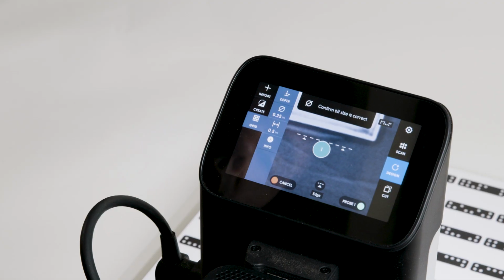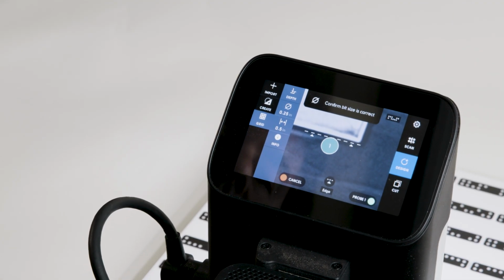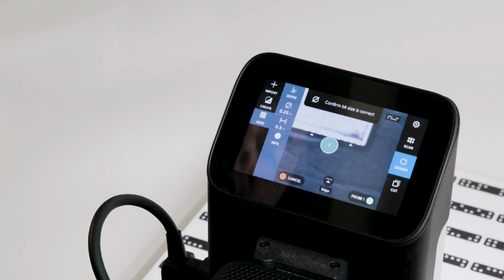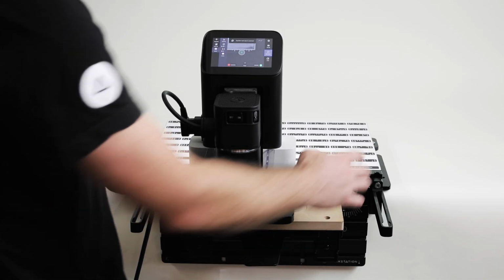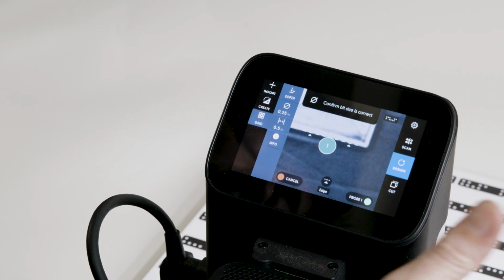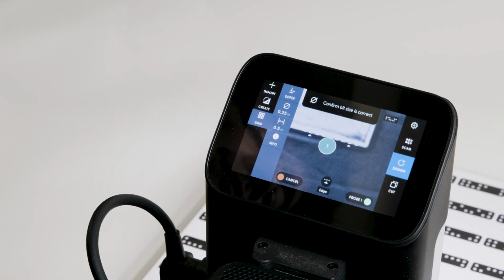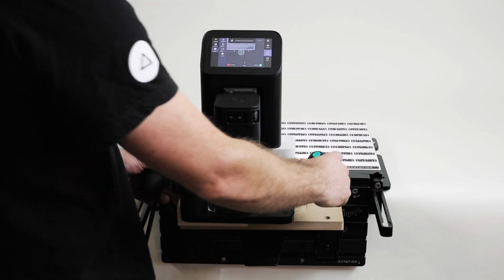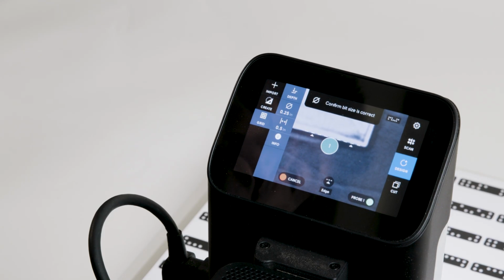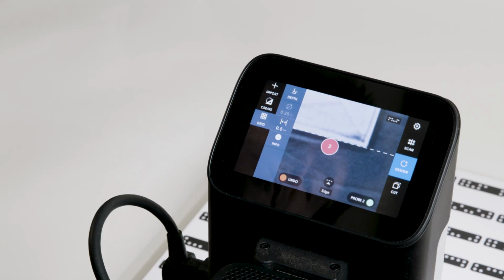So I'm just going to bring Origin forward, and you remember the cutter's down below the surface here. So it's very lightly physically contacting the surface. That's exactly what we want. We don't want to mash it against the surface. It's a precision measurement. I don't want any deflection. I don't want my wood getting squashed or anything getting me an inaccurate reading. I just want a very light touch, and then I hit the green button to probe the first point.